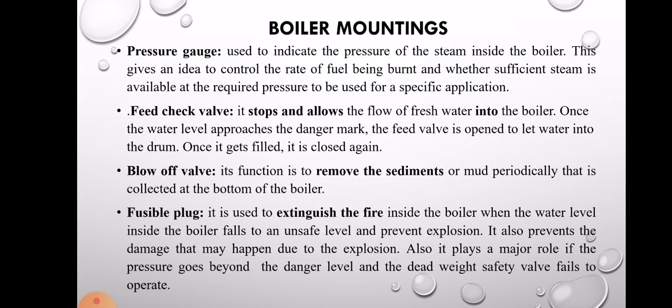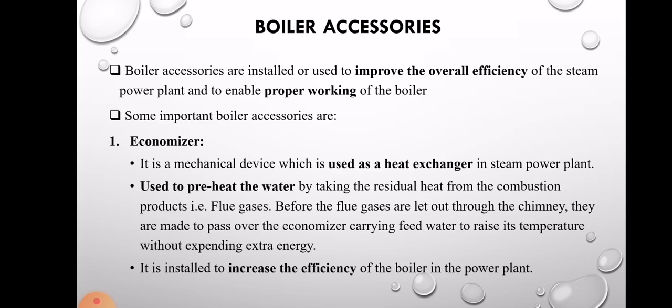Now, in some cases, you can use two fusible plugs, one at the bottom and one at the top. The top one will release the steam and the bottom one will extinguish the fire. Then we come to the last part of our discussion, that is boiler accessories.